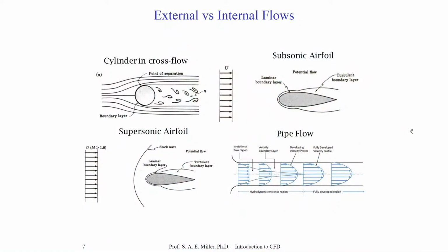In the upper left, we have an external flow, which we've shown multiple times in this class. Flow moves from left to right, and in the streamline shown, there's a point of separation and a turbulent wake behind it. You can also see that this flow is likely a subsonic flow. It's also a flow that contains multiple regimes. That is, there's a laminar flow in front of the cylinder, there's a transitional flow on the side of the cylinder, and there's a fully turbulent wake behind the cylinder. That's very frustrating because we'll have to have a CFD solver that can capture all of these effects simultaneously. It could also have effects of compressibility, so you may not be able to make the incompressible assumption.